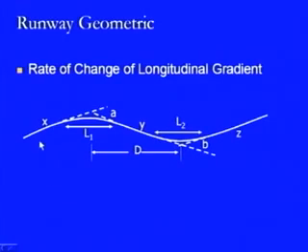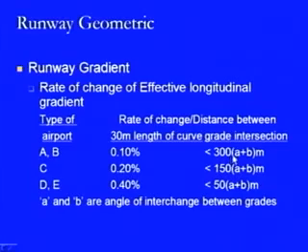Here there is an x gradient which is going up, and there is a down gradient y, and again probably an up gradient as z, and this is the profile of the runway strip. In this profile, A is defined as the change in the gradient at this position from x to y. Similarly, from y to z there is a change B. So this A and B, which we have seen as 300 times of A plus B, 150 times of A plus B or 50 times of A plus B, are found from those conditions.